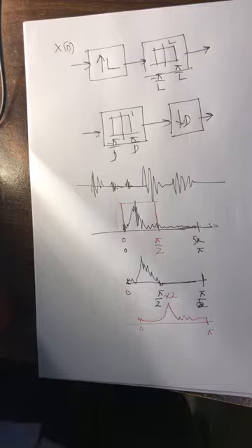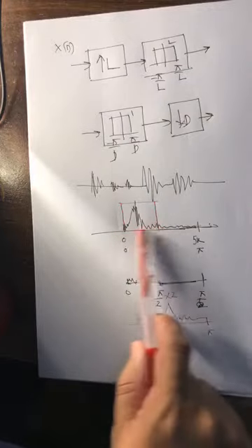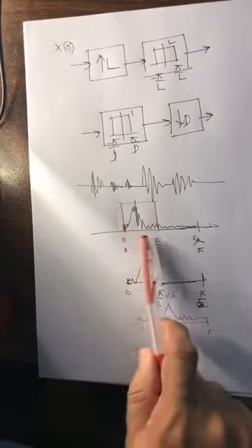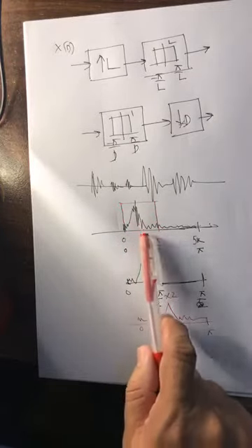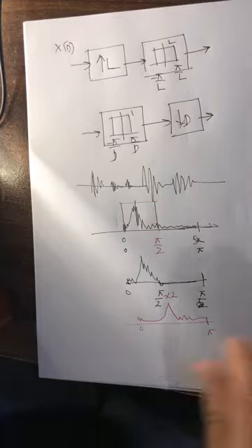You can directly throw away samples, but then your voice will alias, and this low energy will get into this part of the spectrum and it'll try to disrupt the voice which you really intend to keep. So decimation, we have seen an example of voice in MATLAB. We have seen how you pass it through a filter. You should design a pi by 2 filter and pass your signal through that filter.